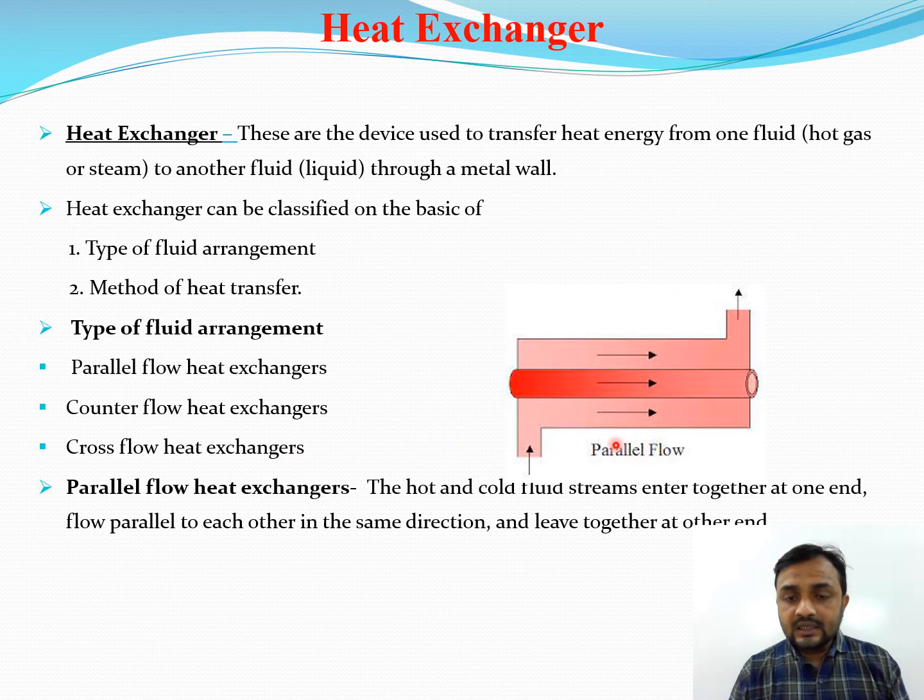This figure shows the parallel flow heat exchanger. What is a parallel flow heat exchanger? In a parallel flow heat exchanger, the hot and cold fluid streams enter together at one end. Hot fluid stream enters at this end, cold fluid stream also enters at this end.